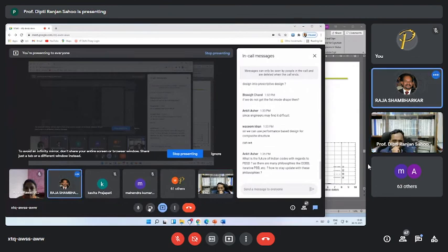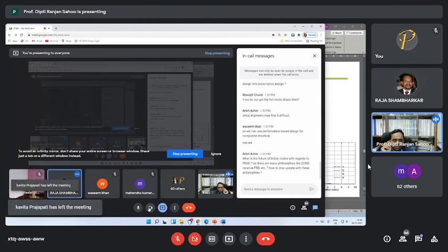The basic concept is that you should have a continuous load path. If you are applying a force at the top of the roof, there has to be a continuous load path so that the load is transferred to the footing without many discontinuities in between.